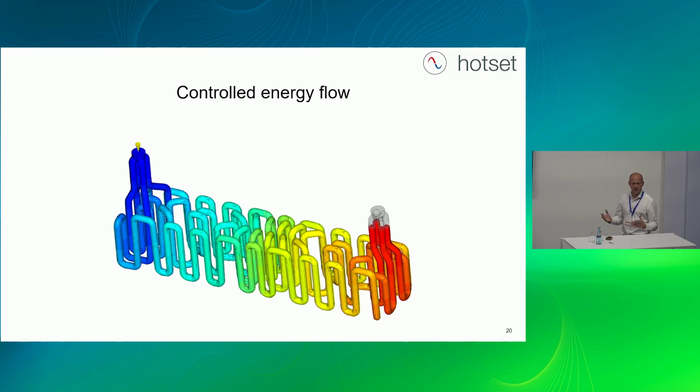What happens then is he starts his process, injects the material onto a higher temperature surface, and then he cools it down. He shocks it when the part is completely filled inside of his insert, and because of the big heat exchanging surface inside of his insert, you are able to transfer the energy from the plastic very fast into the water and freeze the part, but it's completely filled. And after that, stop circulation of your water. And he said, okay, I will try it.